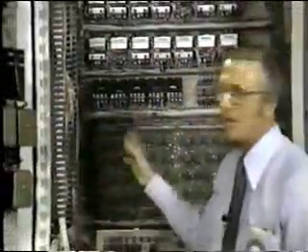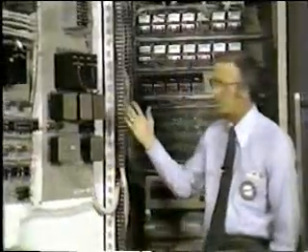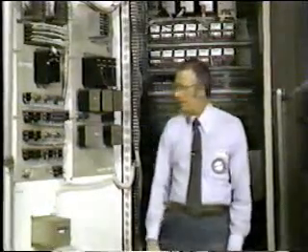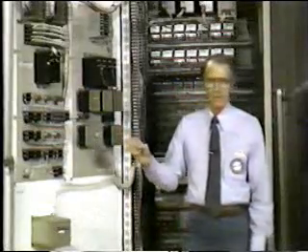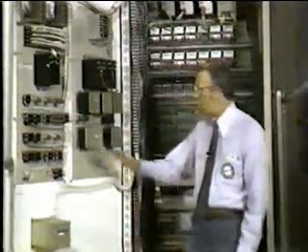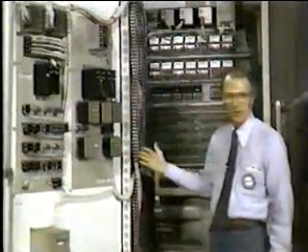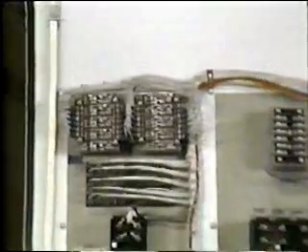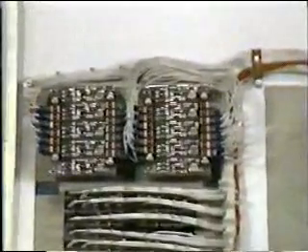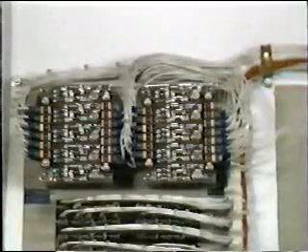Most of the protective monitoring systems are a part of the DC control system. Each of the monitoring systems can shut the engine down when a malfunction occurs to prevent damage to the package or the surrounding environment. Now, before I describe each of the monitoring devices, let's take a closer look at how the engine is shut down on a malfunction. All of the monitoring devices are connected to one of these malfunction controls located here on the back of the console door.